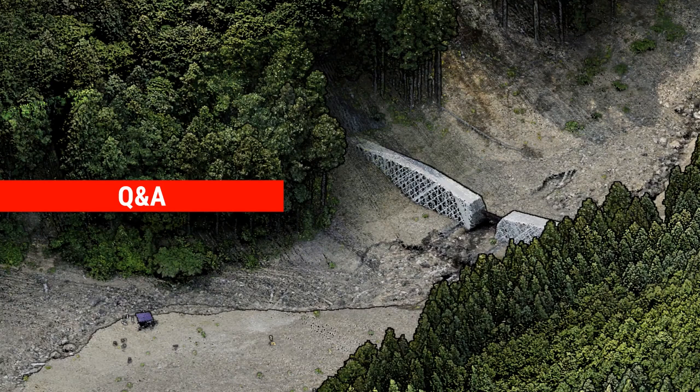Because the geoid undulation at where the vehicle was may be different than the geoid undulation of where the point is that you shot. So applying the undulation to the trajectory isn't technically the most accurate solution, but yeah, people keep asking for it, and you can apply a geoid during export of a trajectory into another format like SPAD or POF.